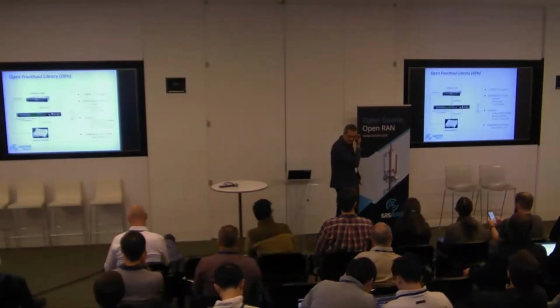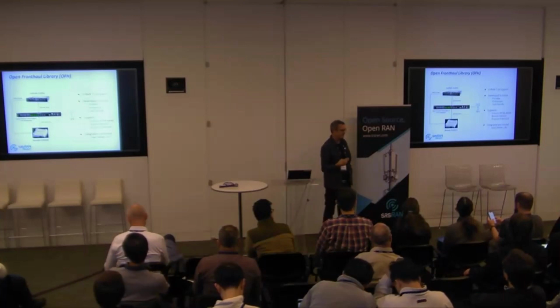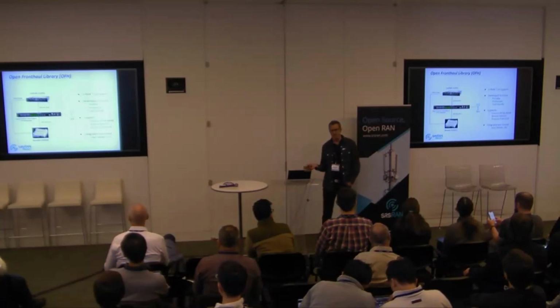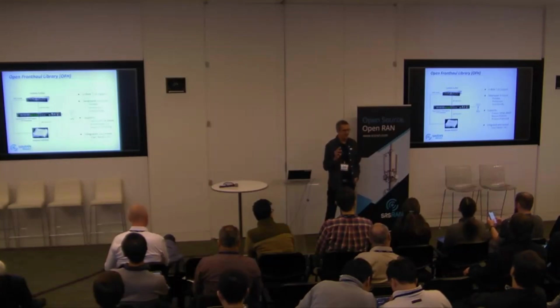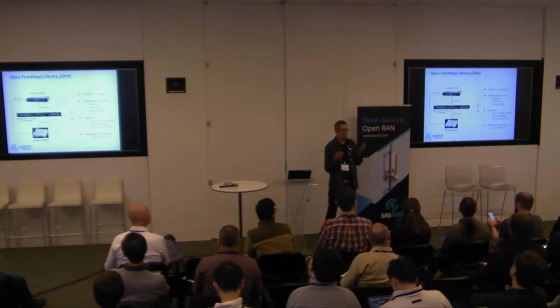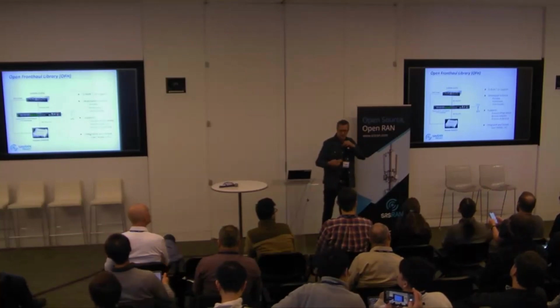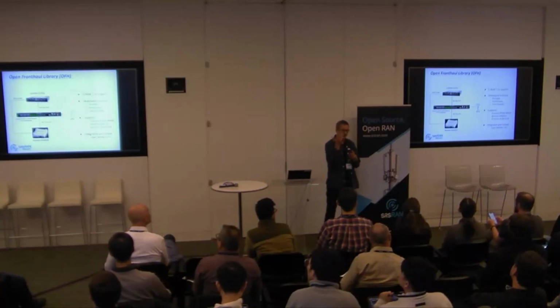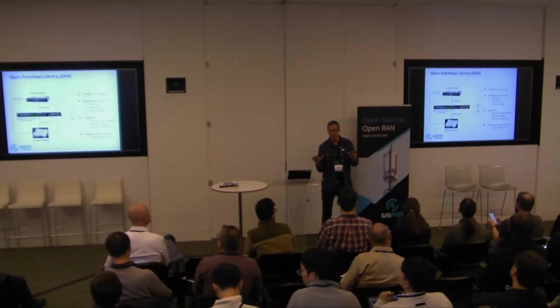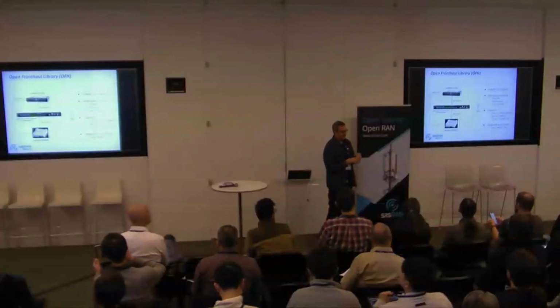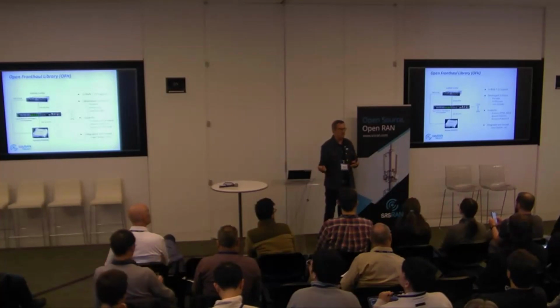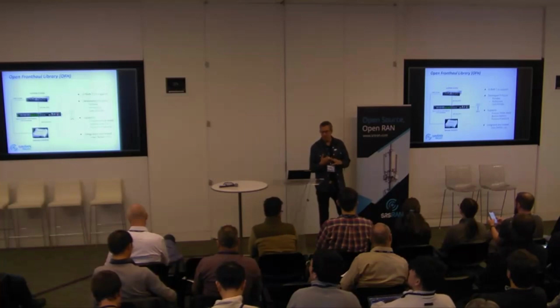The first thing that we tried when we started looking at this was, okay, let's see what's out there available and see if we can reuse it to avoid reinventing the wheel. What was available was XRAN. XRAN, don't confuse with FlexRAN. Both Intel, FlexRAN is the full PHY and builds on top of XRAN. XRAN implements only the 7.2 interface. So that's essentially building the eCPRI packets with the ORAN fronthaul protocol to control an RU. This is user and control plane.